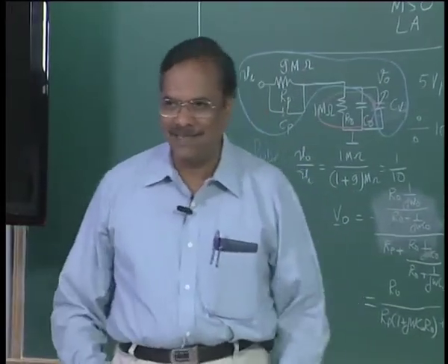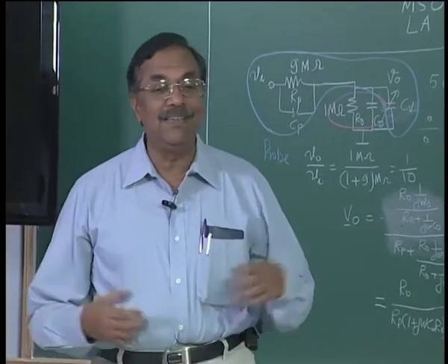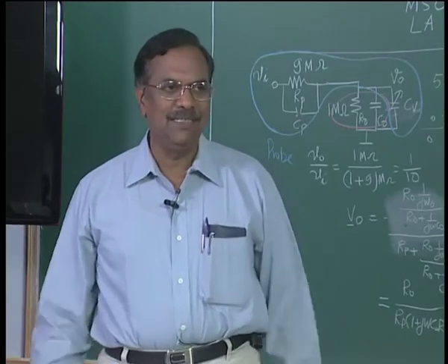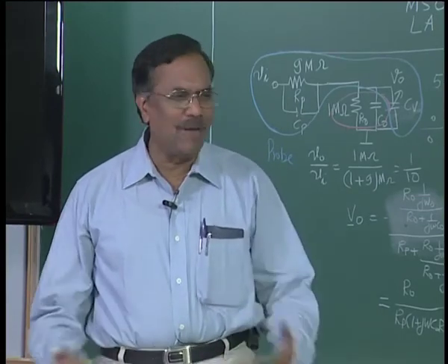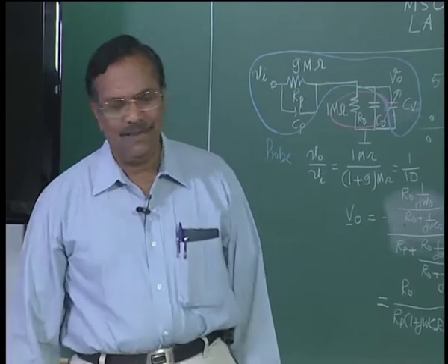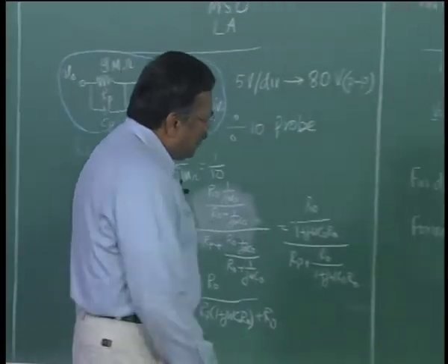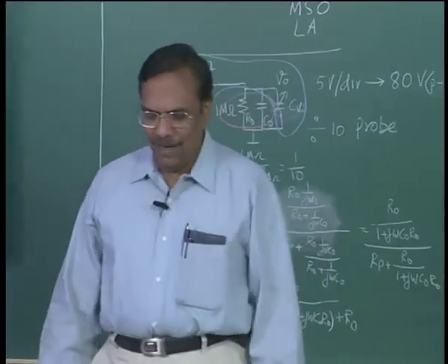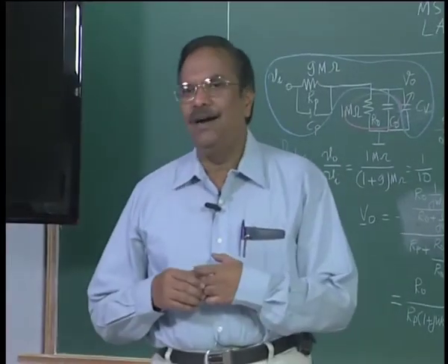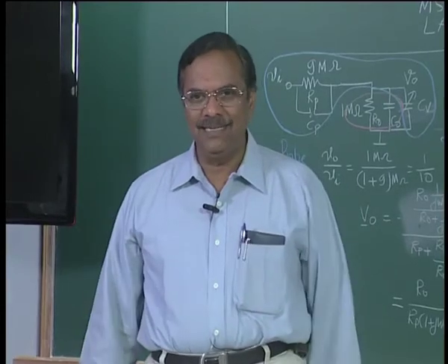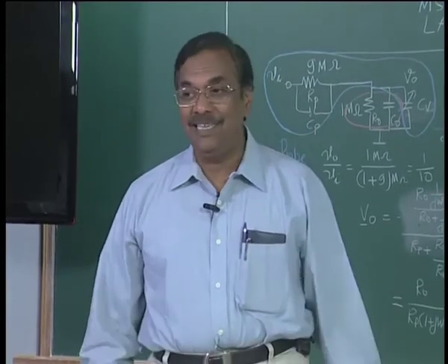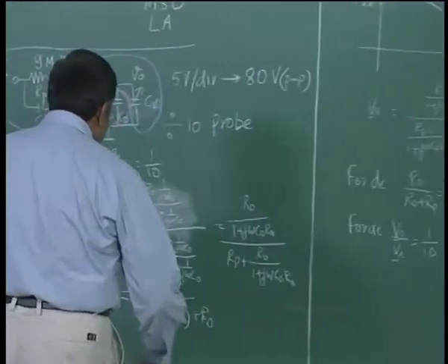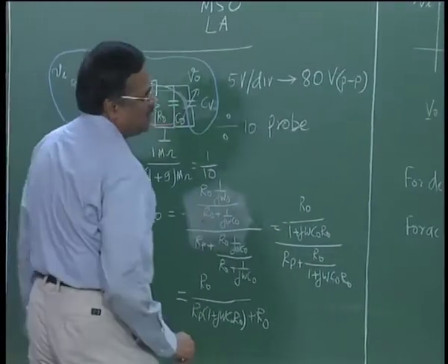Measuring 2 capacitances and finding that the ratio has to be 1/9 or 9 times is very difficult, although these are small capacitances, picofarads, right. So people realized there must be an indirect way of achieving the same condition without actually measuring the capacitances, right. That is where the square wave comes into the picture.